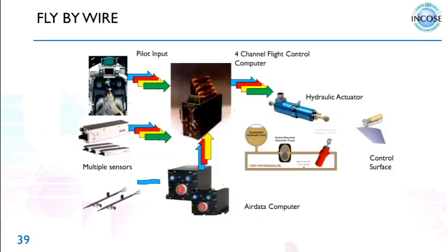And this is the fly-by-wire I was talking about. So you have quadruplex channels. You have four channels, four computers, all four sensors. So this is the kind of thing which is there in the Indian LCA program, and all four because of redundancy, because there is no backup here. So if one computer fails, the other three will work. If two fail, another two will work. And perhaps he can't fly it, but at least he can land the aircraft. Okay. So this is how an actual architecture looks like, and this is an electronics domain. It is not an aerospace domain. Okay.